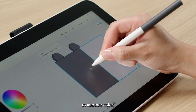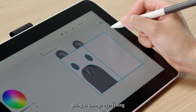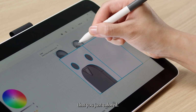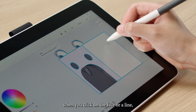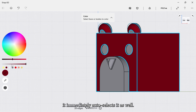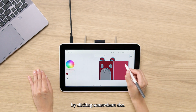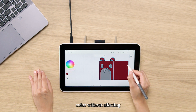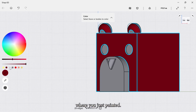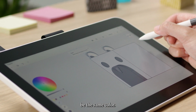Now, if you want to jump to another color, you may notice that right away when you select another color, it's going to change everything that you just colored. This is because when you click on the face or a line, it's immediately auto-selected as well. So if you don't want those colors changed, remember to deselect it by clicking somewhere else. Now you can select another color without affecting where you just painted. Then we want this area to all be the same color.